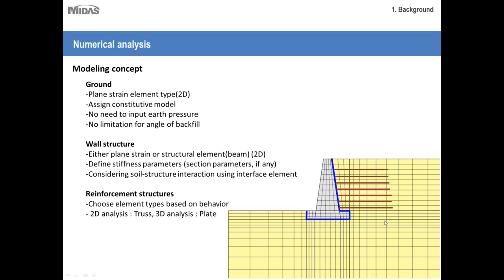Right now you can see this is just a 2D representation, and here you will see this is a single line element for reinforcement. But let's say this model was not 2D and it was 3D, so it will have a third dimension in that direction. So this 1D member will then span in 2 dimensions, and therefore this will no longer be a 1D member, it will be represented by a plate member.